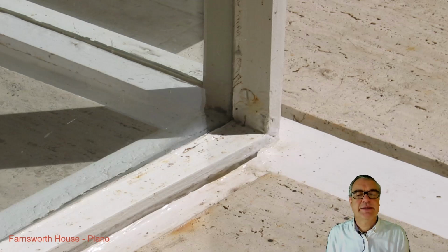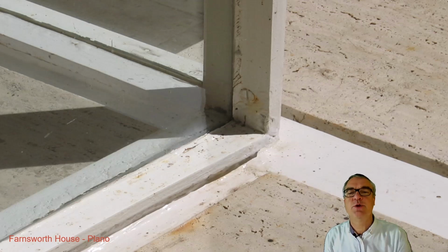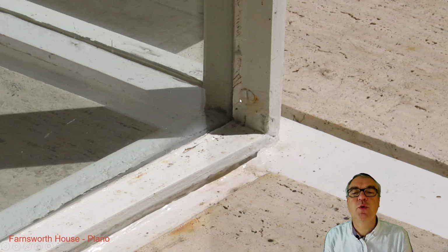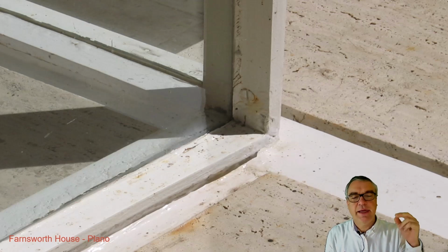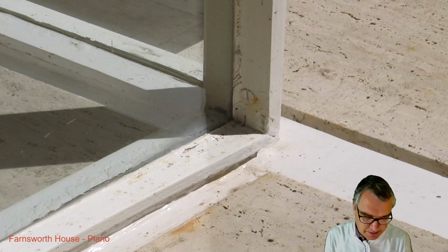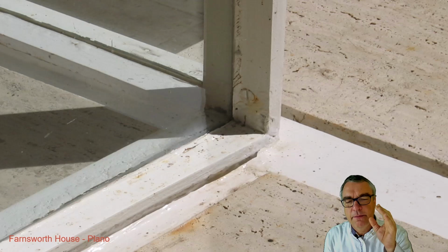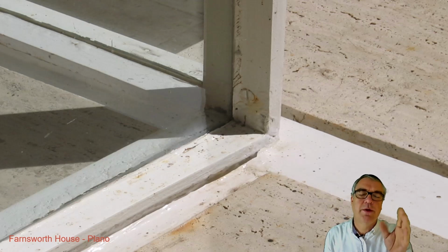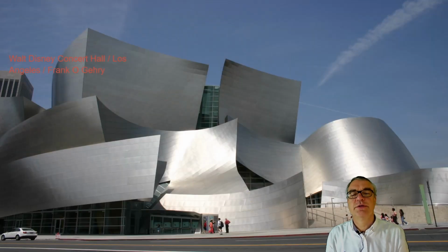With just one layer of glass, you're able to create very slender steel structures which are craftsman manufactured, brought in position, built on site, and even screwed in position, which we would not be able to do in our modern IGU, insulated glass unit systematics, where we have to take care of any energy transport within this system. Interesting experience. So super nice architecture at the level of its time, but nowadays impossible because of the technical demands which we see for solutions nowadays.